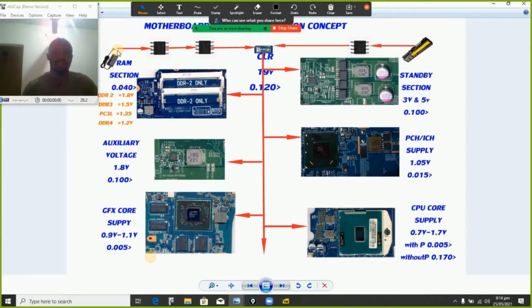If the system is about to power, or it has an issue of power, or power without display, then between the hair and the toe there is a problem. That is, there is a problem between the charging port, which is the source of the power, or the battery, and the final destination, which is the LVDS, the connector of the screen. So that means there is a problem within that section. Whenever we're talking about a motherboard, it's a step-by-step approach. That's just the summary. If one step is not fulfilled, then the next step will not be fulfilled.